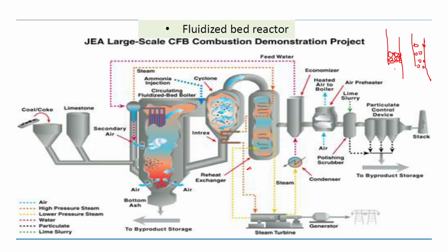In a fixed bed, the contact between the gas, that is the steam and oxygen we provide, and the coal sample is not that good because of the packed structure. But in a fluidized bed, when we provide the oxygen from below, due to the very fine particle size, the particles form a suspended formation.